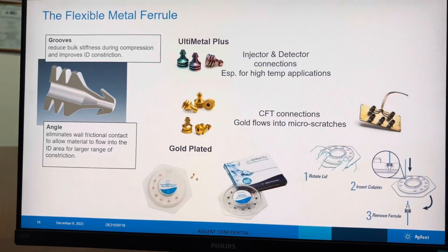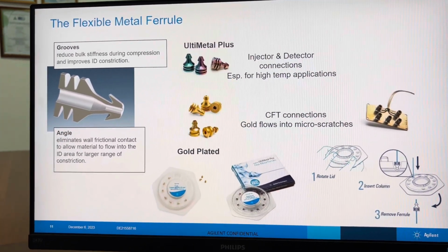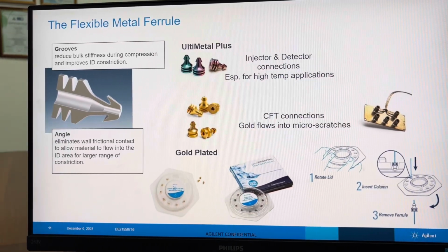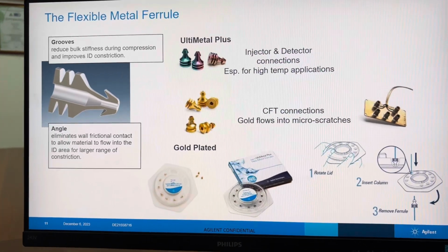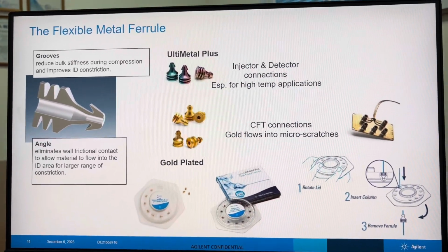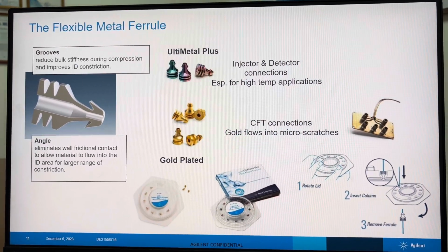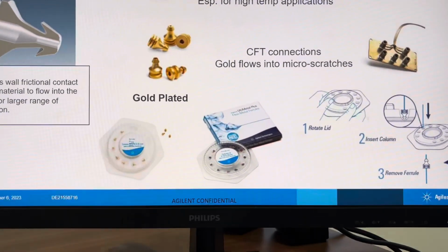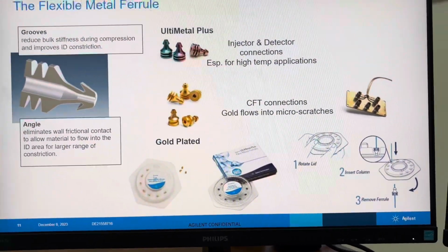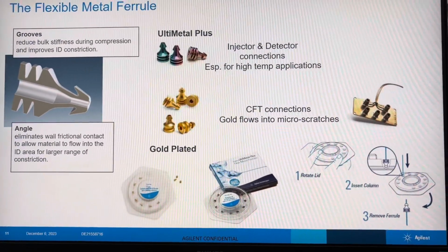You just need to rotate it and collect the ferrule which is required from that location, and then install it, so that the other ferrules are not in contact with our hands or the tools or even the environment, so that inertness is protected until we open and install. That is the main reason to have these kinds of packings: to protect our analysis.